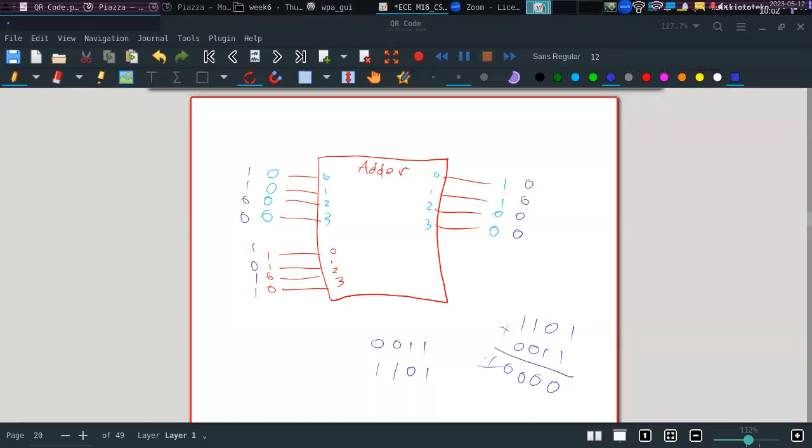But we don't care about this. As you could say, this one will be in cout, but we are ignoring cout right now. So it will perform the correct operation. So far, good. Where again, this is where the two's complement actually makes it. We only need an adder to perform both addition and subtraction. It's just a matter of complementing the number we want to subtract.